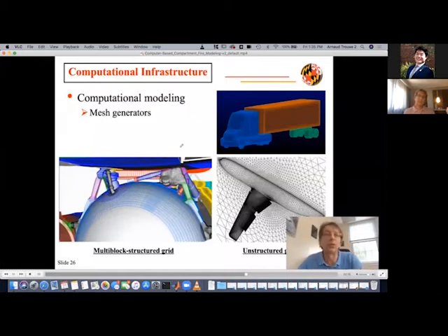Typically for complex geometries, you need mesh generators that conform to the complex solid surfaces and complex geometries of the solid objects of interest for the fire scenario. By the way, FDS is limited to a simple rectangular shaped computational mesh, where, for example, a tool like Firefoam has a more flexible meshing capability ranging from structured to unstructured grids.